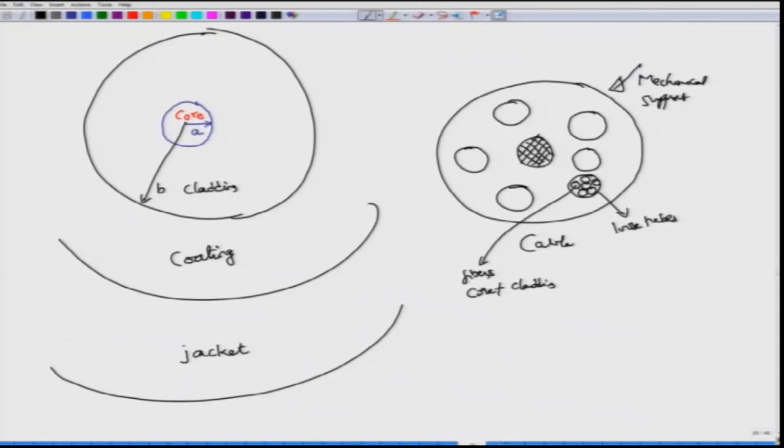We will assume that the cladding radius is so large compared to the core that we can think of this cladding as being an infinitely big medium. So, you essentially have a single circular rod structure, which is the core, with all of its properties that are of interest for fiber light guiding, and then surrounded by an infinite medium of cladding of different material properties. There are some sophisticated mathematical techniques which one has to use if the material properties are completely random, but luckily we do not have random material properties.